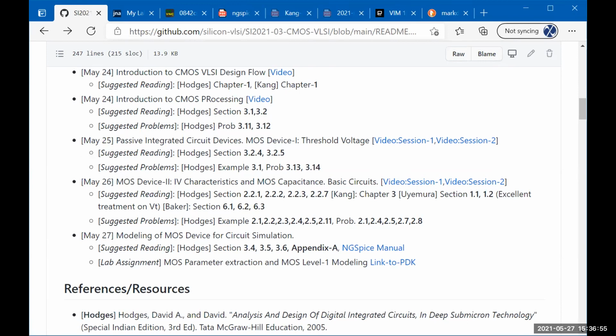So for example, what you're doing in the lab right now, you're doing the slope and all that. I've never used ICCAP, but in ICCAP, what you do is you give these slopes, you give some bare minimum stuff, and then from that, it calculates all the derivative parameters and creates the BSIM model or EKV model or IGBT models or whatever other models. There are plenty of other models people use for different devices and so on.